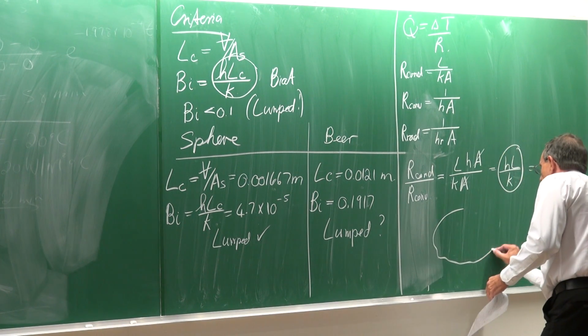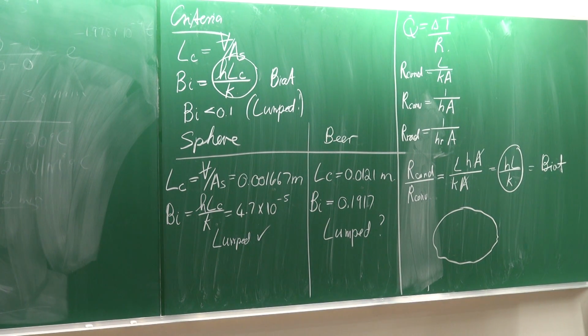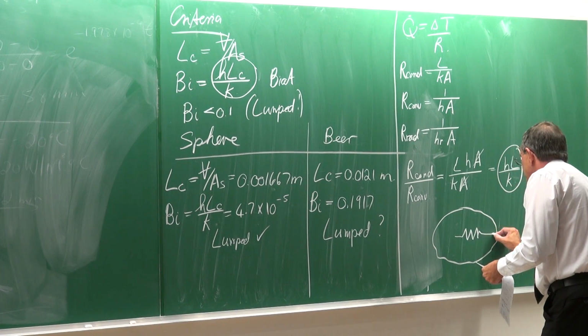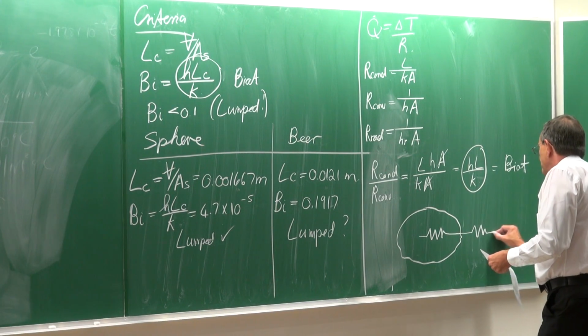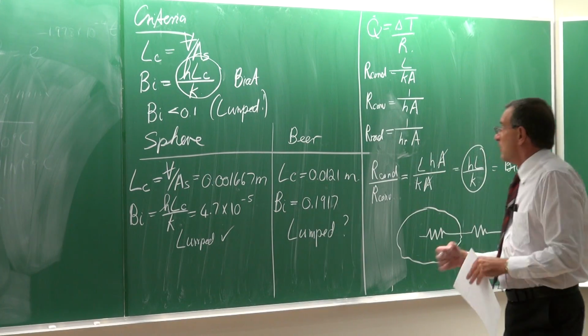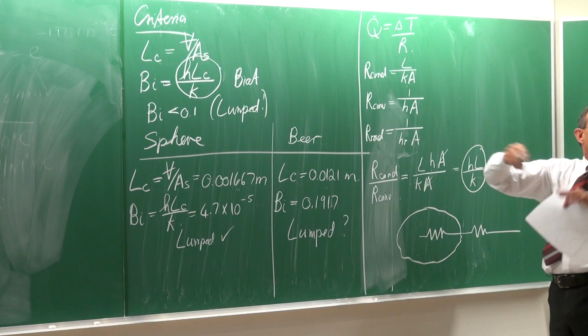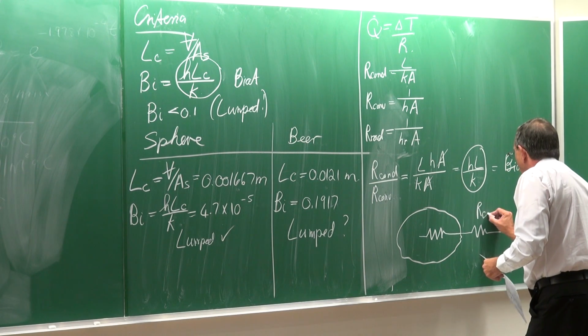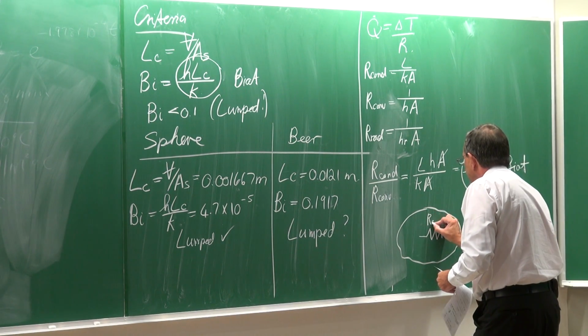So if we think fundamentally of the body we want to consider, for which we derived that equation, it could have any surface, any volume, etc. This body will have a certain resistance, which is determined by what? The resistance would be determined by the thermal conductivity and its geometry and length. You agree? And then on the outside there will be the convection from the environment. So this is the ratio of convection to conduction.